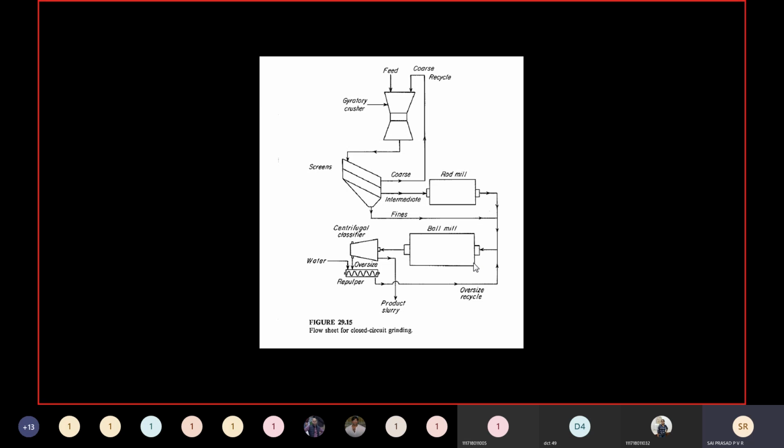Remember this. Here in this ball mill, we are going to send the water, and then we are going to control the wet fraction, and after the crushing is over, it is sent to a centrifugal classifier. A classifier is a device which separates the feed into two fractions. One part liquid and heavier particles, the second part liquid with smaller particles. Remember once again, a centrifugal classifier is a device which separates the feed into two fractions. The feed is solids plus liquids. Solids with heavier sizes are sent into one particular section. Solids with smaller sizes will go into a separate section.